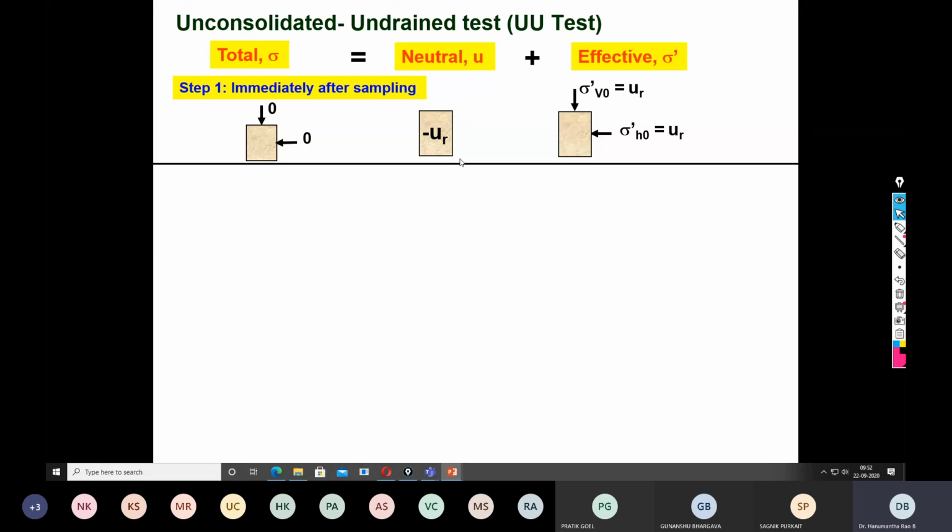But if you take out that sand sample and take it to our technical analogy, where on the sample sigma 3 is 0 and sigma 1 is 0, the sample is still able to retain its geometry. That is because of capillarity, or the capillary pressure, but here it is termed the negative pore water pressure.